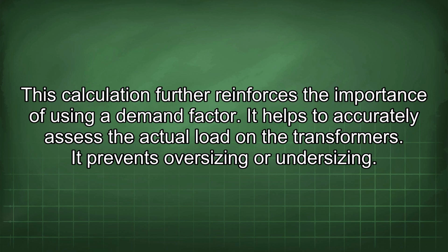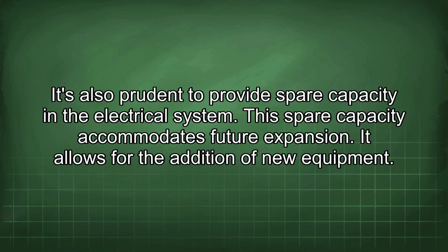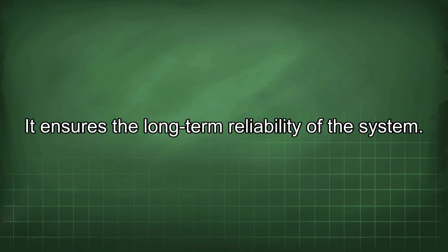This calculation further reinforces the importance of using a demand factor. It helps to accurately assess the actual load in the transformers. It prevents oversizing or undersizing. It's also prudent to provide spare capacity in the electrical system. This spare capacity accommodates future expansion. It allows for the addition of new equipment. It ensures the long-term reliability of the system.